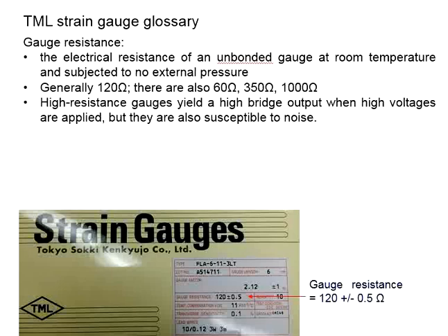You know that when it comes to measurement, it doesn't mean that the more sensitive it is, the better. When the measurement is too sensitive, there may be noise, and this will affect the results. The sensitivity should be just enough, not too low and not too high. Personally, I feel 120 ohm is already sensitive enough. You will see fluctuations in the reading, even though you did not induce any force onto the material. Unless you need it to be highly precise, 120 ohm is good enough.